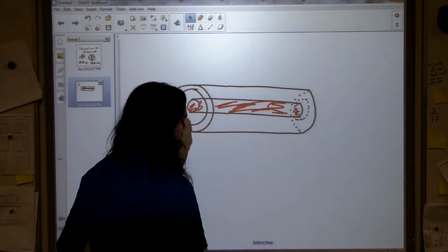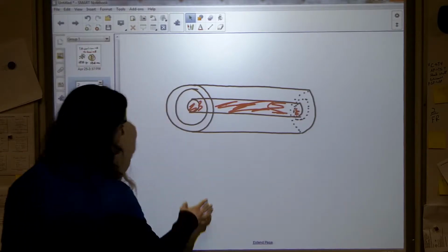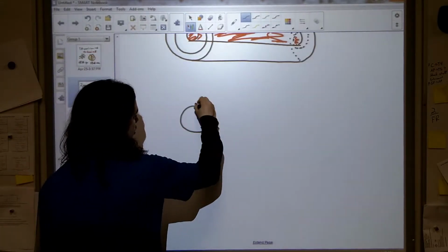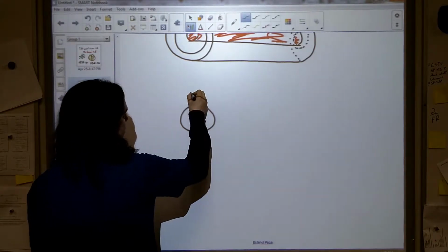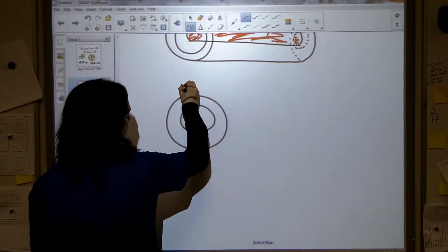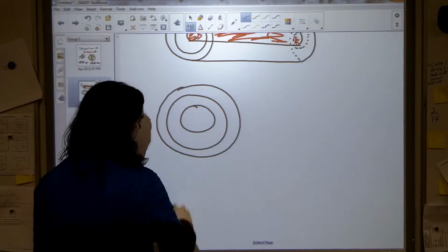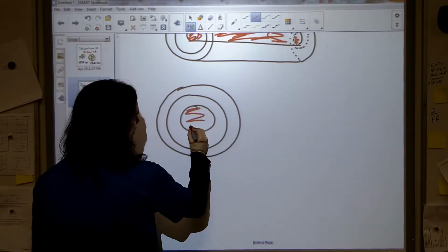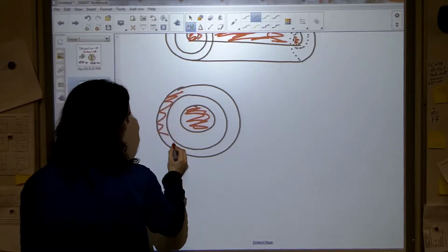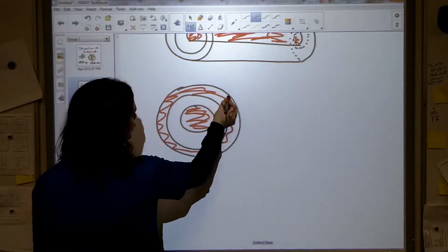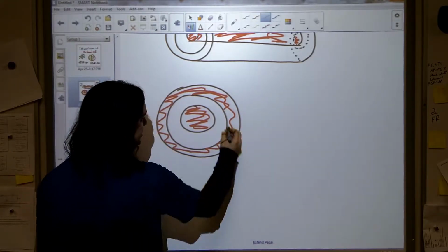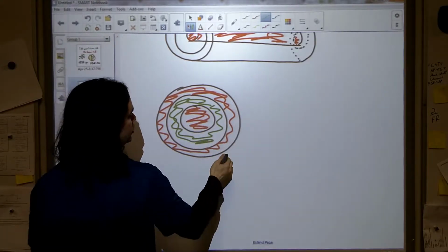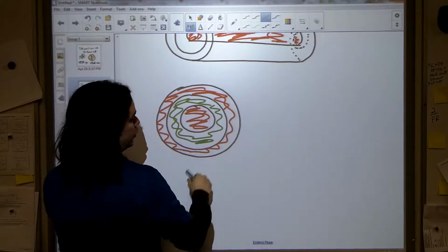All right, here's what we're going to do. We're going to say that we have, so from a side view, it looks like this. We've got a wire in the middle, and we've got a shell that goes around the outside edge. So we've got some metal here, and we've got some metal here. And usually they are separated by some material, a dielectric of some kind, so that charges can't go from this one over to there.